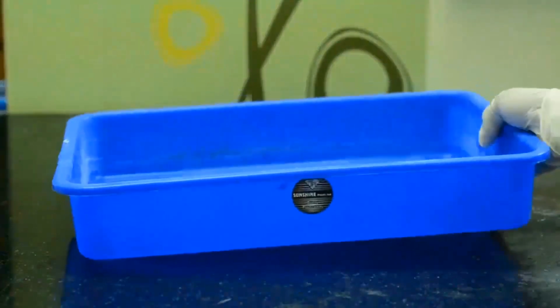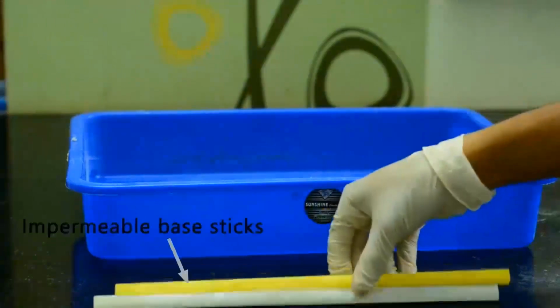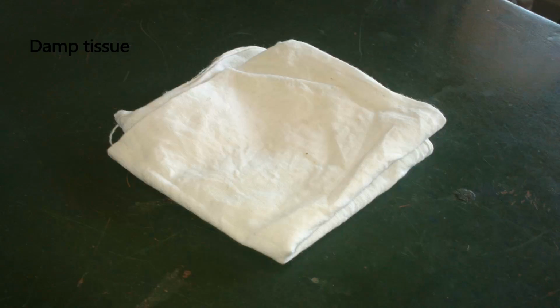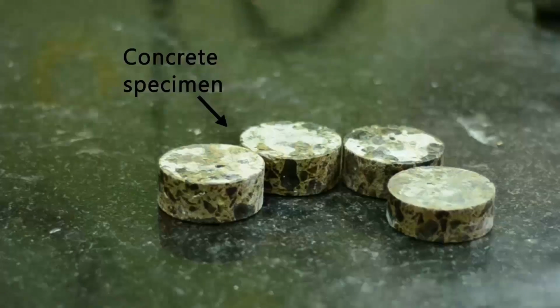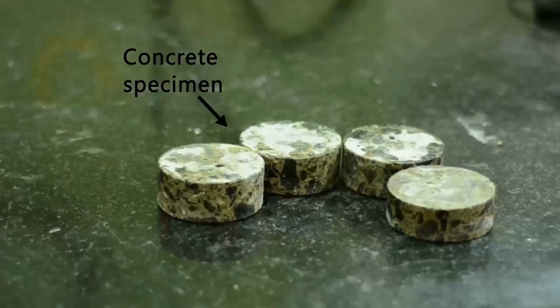We require the following apparatus and materials: plastic or stainless steel tray, impermeable base sticks, saturated calcium hydroxide solution, a damp tissue or cloth, a weighing machine, and concrete specimens of diameter 70 plus or minus 2 mm and thickness 30 plus or minus 2 mm.